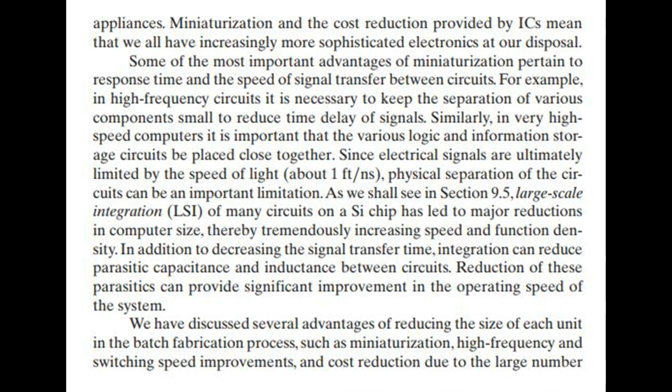Miniaturization and the cost reduction provided by integrated circuits mean that we all have increasingly more sophisticated electronics at our disposal. Some of the most important advantages of miniaturization pertain to response time and the speed of signal transfer between circuits. For example, in high-frequency circuits it is necessary to keep the separation of various components small to reduce time delay of signals. Similarly, in very high-speed computers it is important that the various logic and information storage circuits be placed close together. Since electrical signals are ultimately limited by the speed of light, about 1 foot per nanosecond, physical separation of the circuits can be an important limitation.